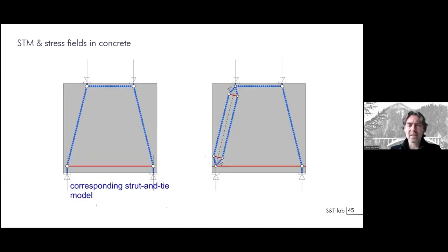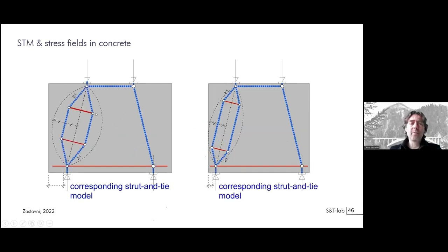And here we have the full modeling system with graphic statics demonstrating the compression trajectories as struts and the tension trajectories as ties. Going back to this, normally you have to consider along the strut the same mechanism, and you have to implement this bulging. And depending on the place where your limits are, you will be developing strut-and-tie modeling in this case. So this is the simple and this is the detailed system. This shows you that you have to take into consideration compression and tension perpendicular to it.